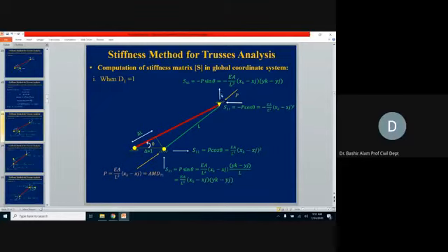And here it will be balancing this one. So it means we need to reverse its direction. It should be looking downward now, or this negative is taking care of that. So this should be downward. In summation of Fy equal to 0, it should be balancing this. So it is minus EA over L cube (XK minus XJ) times (YK minus YJ).